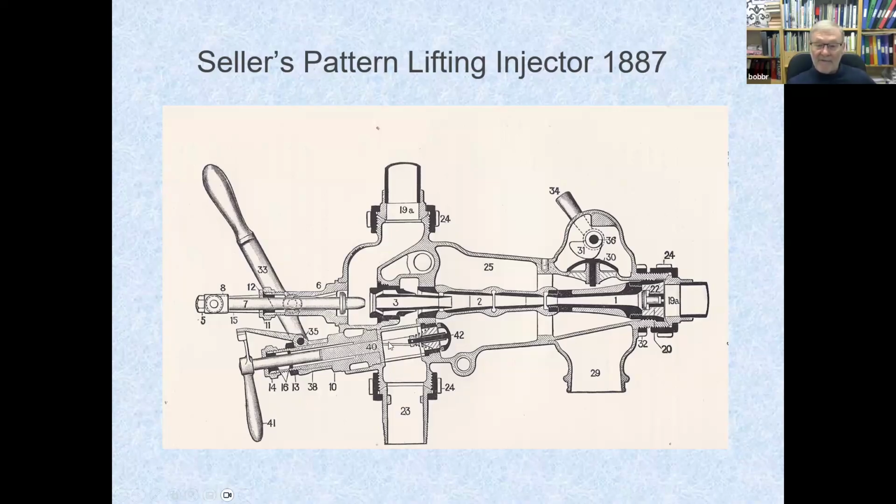They've got a special valve that allows water to be restricted when you start, and you can regulate it on there. And if you pull the valve right open, steam comes through here, through this annular passage here, and also through the main nozzle. And it's very powerful. And at some time, you can open the water up, and the water will flow into here and will be entrained furthermore in through here and through here. And they are absolutely brilliant injectors. And that's the check valve to stop the air going in.